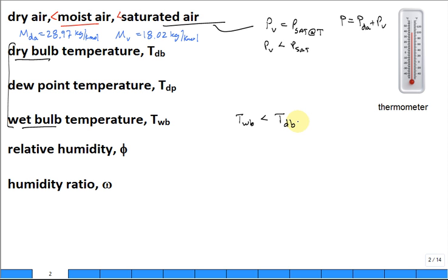If the air is completely saturated, does it have the potential to evaporate? So, no. And so guess what happens to the difference between those two temperatures when it's now 100% relative humidity, it's saturated air? There is no difference in the wet bulb and dry bulb. That sling psychrometer, you'll have 2 same temperature readings. Okay, the wet bulb is equal to the dry bulb when it's saturated air.